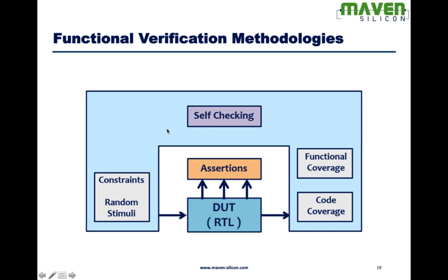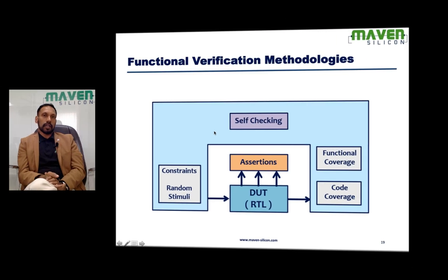We discussed the simulation process, but we don't want to consider functional verification as something like, to run simulation, we need to write a test bench. Yes, we have written a self-checking test bench and everything is going to happen like an automated process. The test bench will generate stimulus, it will collect the output, it will compare the output with the expected values, everything is going to happen, and this is called simulation, and functional verification is over.